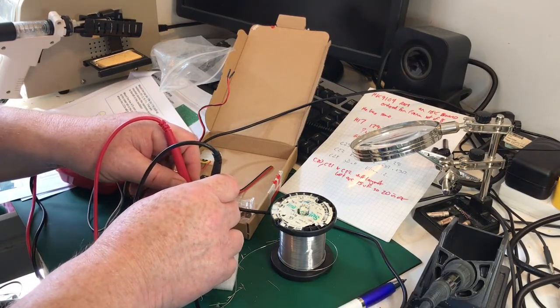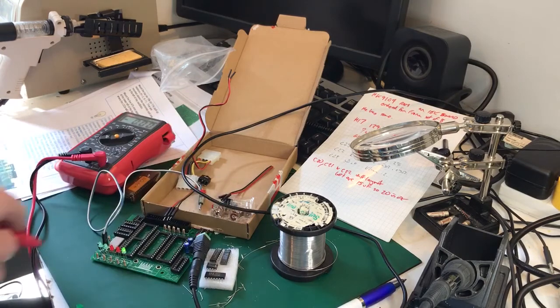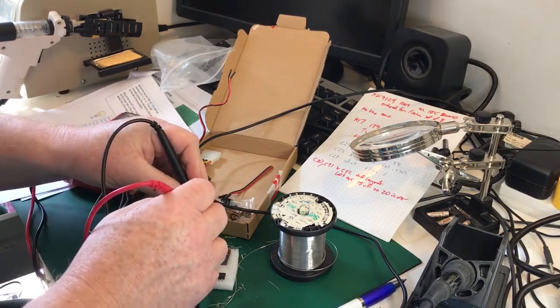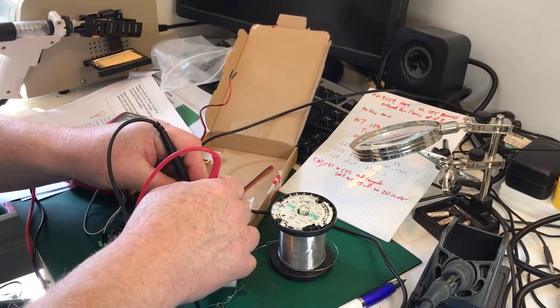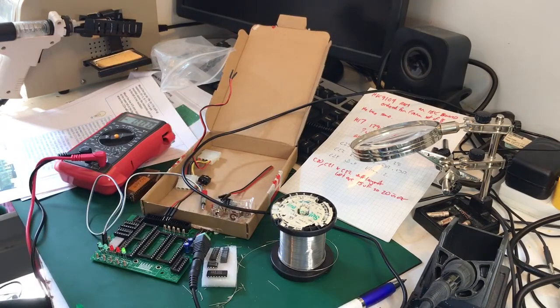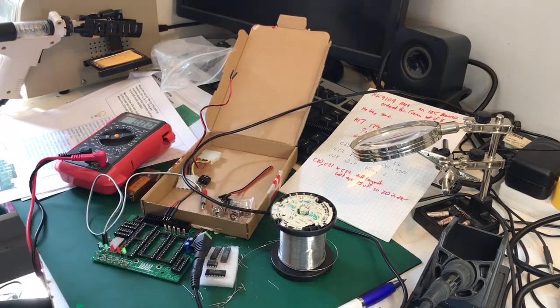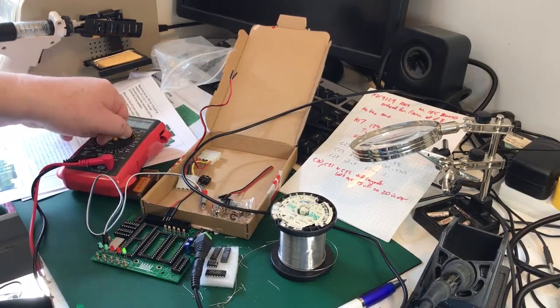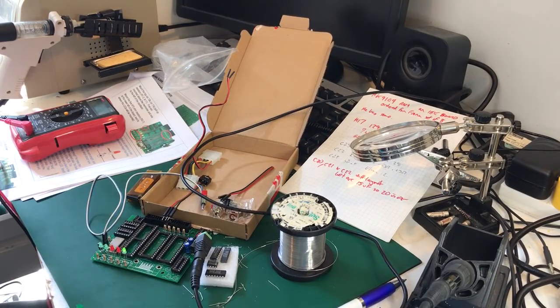Let's check the other chip. It's not far, it's 5 volts the other way up. You've got to watch it, some of the chip orientations are the other way up. 5 volts there. Okay. So that's looking good. The regulator's operating, not under load. So we're ready to go. So I'll plug the PIC in. I'm going to check the PIC pin out and just make sure I haven't made a mistake.